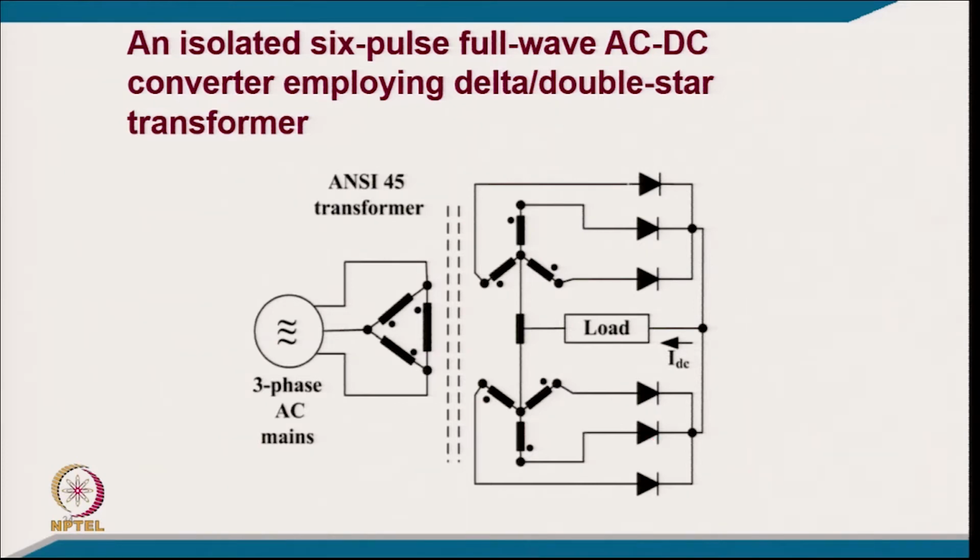So, one diode's losses are reduced. When we are working at a very low voltage, a typical example may be 12 volt, the drop of one diode itself may cause losses of 3 to 4%, even more for very high current and very low voltage applications. Even if you consider the diode drop as 0.7 volt, 0.7 volt compared to 12 volt is not less than 4% or 5% losses in one additional diode if you take a bridge configuration. So where losses are very important, especially in low voltage and high current applications, we prefer this.